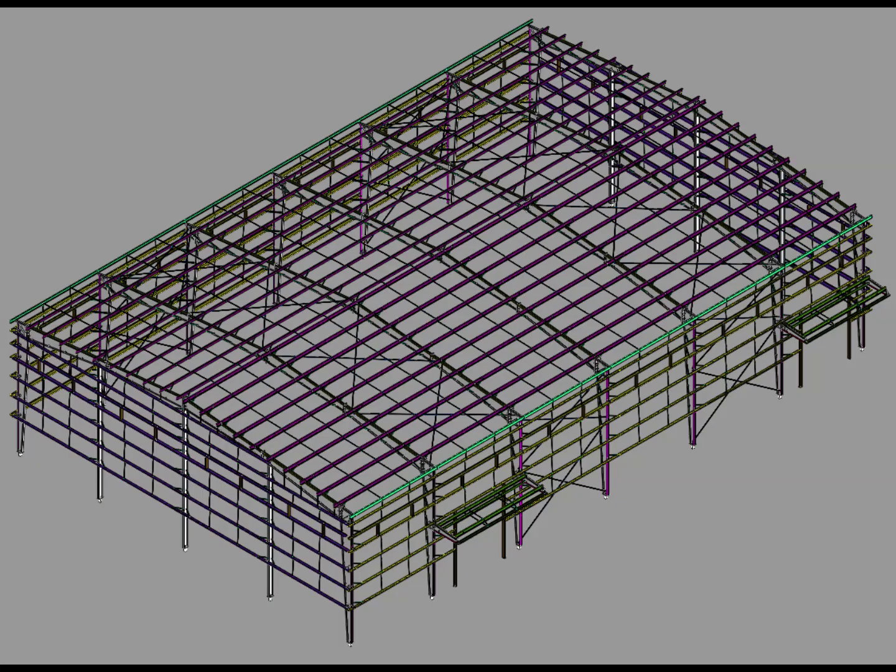Among these members, the sag rods are relatively small compared with the main steel members. Because of their smaller size, they can easily become difficult to identify when we look at the complete building from a distance. That is why a 3D model is very useful for understanding their actual location. Here, the sag rods are positioned between the corresponding secondary framing members. They connect the members across the framing arrangement and maintain the intended alignment of the system.